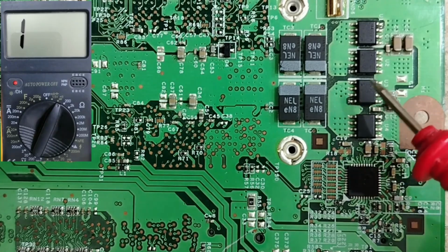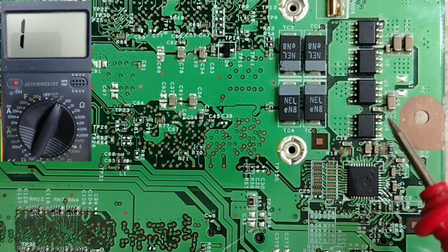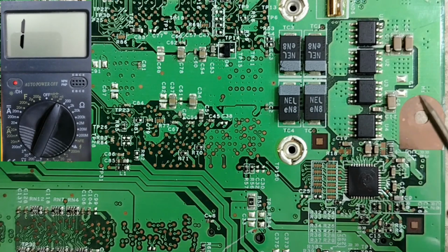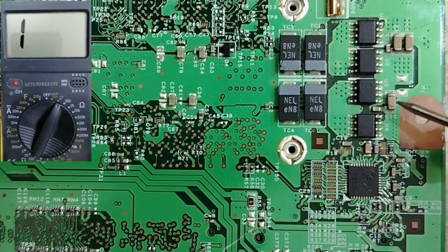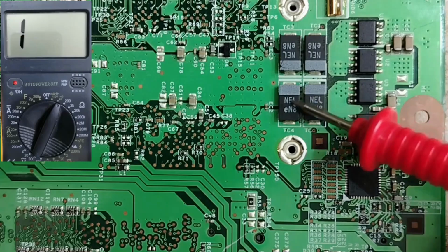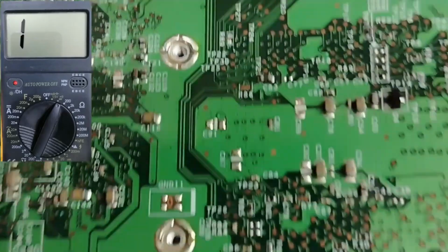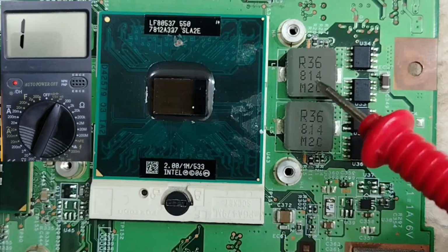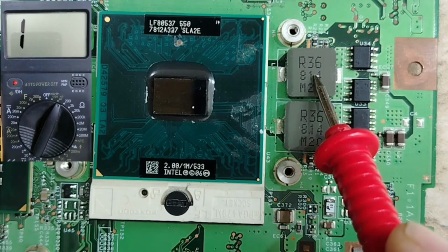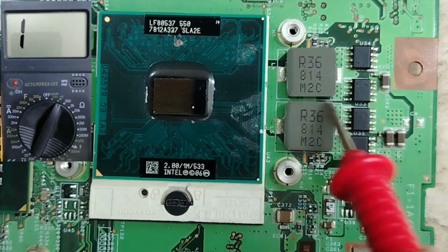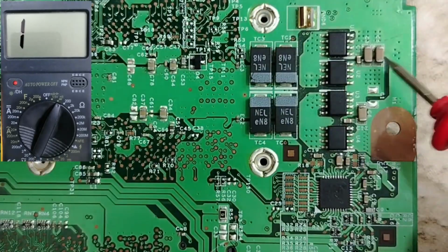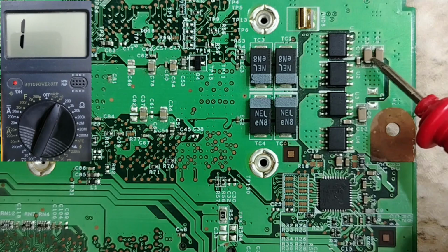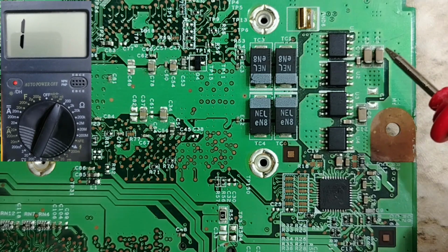So let's first take a look at the CPU circuit and then go step by step on how to diagnose, how to track and follow voltages. As I told you, this is the IC. Here we have MOSFETs, here we have ceramic capacitors, these are 10-10 capacitors, and on the other side we have inductors. Okay, so each inductor means one channel. So this is the first channel and this is the second channel. So here the ceramic capacitors always mean we have the input. We can even check using the multimeter.